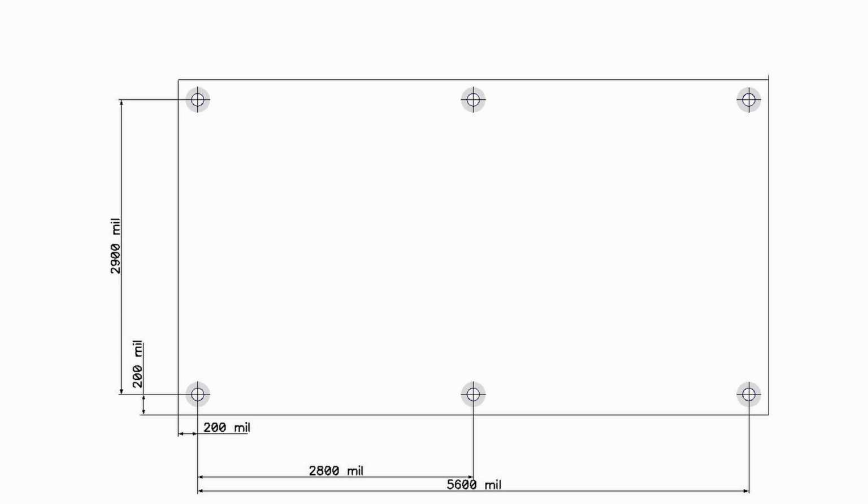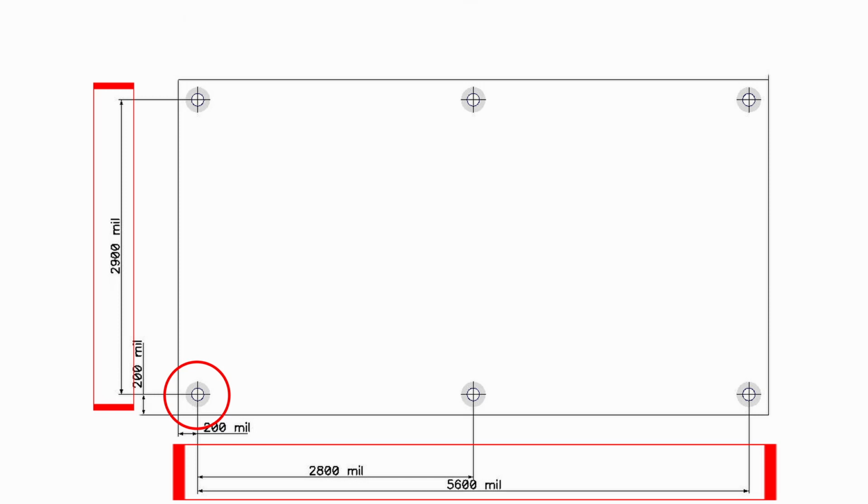We establish a specific reference mounting hole, and then all other measurements are made relative to this mounting hole. The relative distances for mounting holes and the positions of components and the like are held to a much higher tolerance than the dimensions of the board. So now let's take a look at our enclosure.